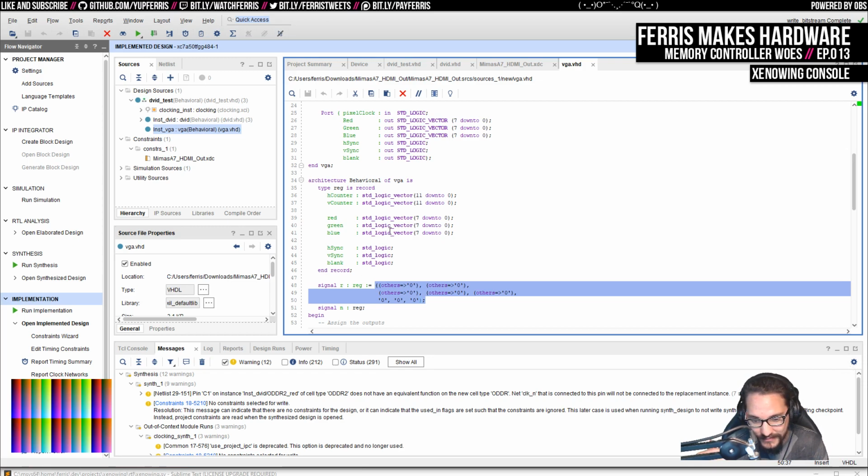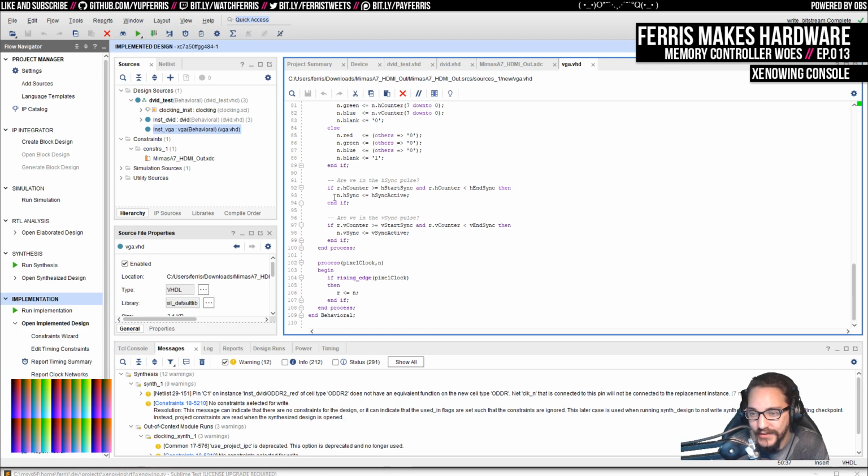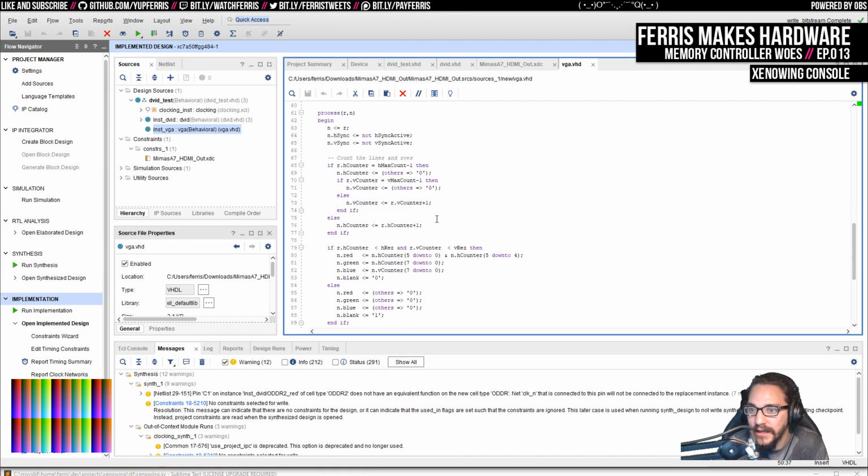So in fact, the clock is going to stop, the output clock at least. But these registers probably still hold their value. And it might also be that the logic here is so simple, and when these counters reset it's so simple too, that they might just end up being back in sync after a while, even if they're wrong. So it's a very simple design here. But I read about that too, that if you're targeting an FPGA, it's sometimes a good idea to just not have resets, because the resets will